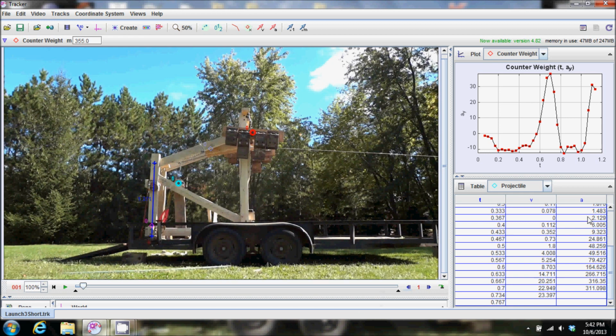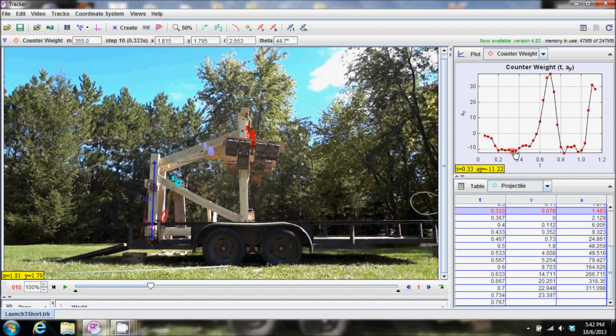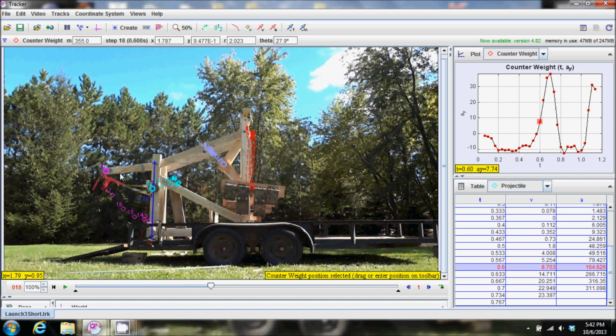The problem with that was when my arm was here is where I was getting my counterweight stall. My counterweight had fallen down a little farther, the arm was straight back, and I could only get it to throw up or backwards. So when I realized the stall was happening in the wrong spot, I shortened this chain and put the arm straight down, and then I set the projectile as a temporary measure on this log here.